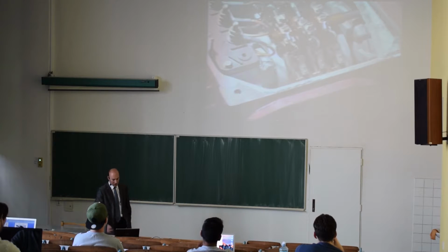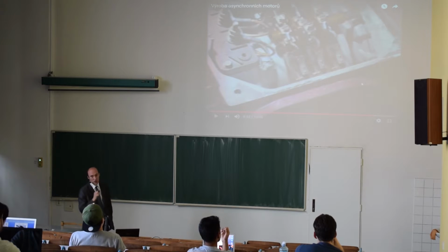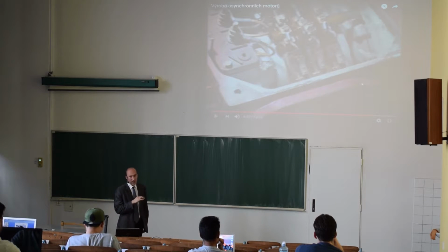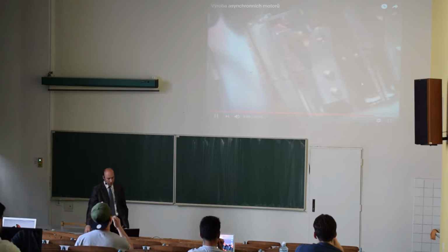So this is the assembly in the terminal box. So those are the 3 brushes that connect the rotor to a terminal box. And as we will see a little bit later, this allows us to change, for example, the torque speed characteristic of the motor to achieve a different startup torque than we would be able to do with a Squirrel Cage motor.